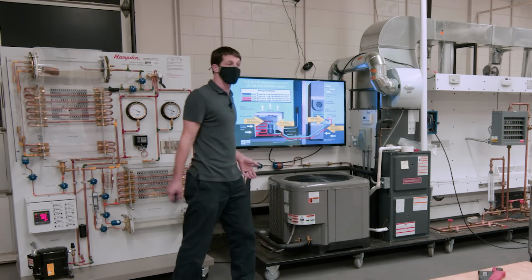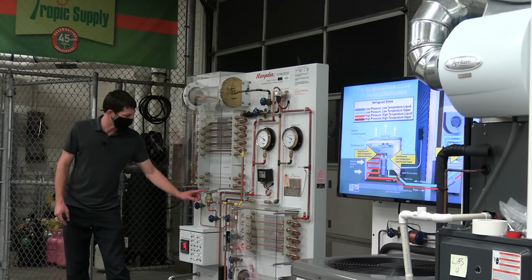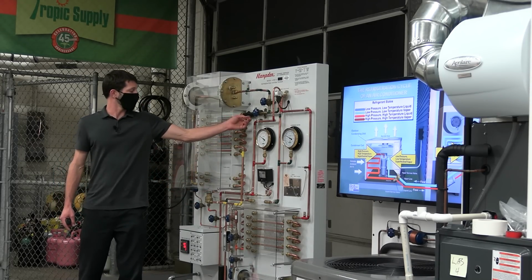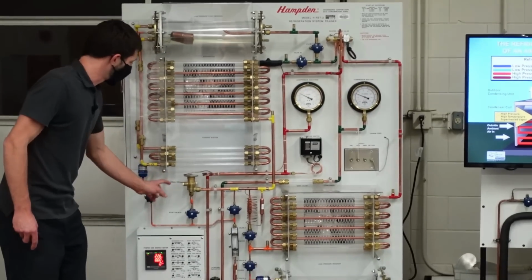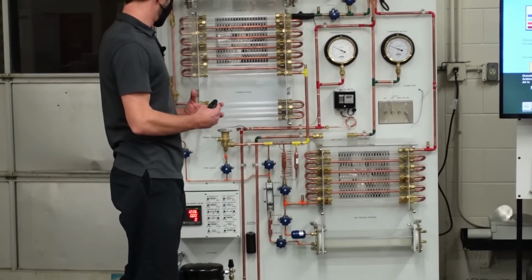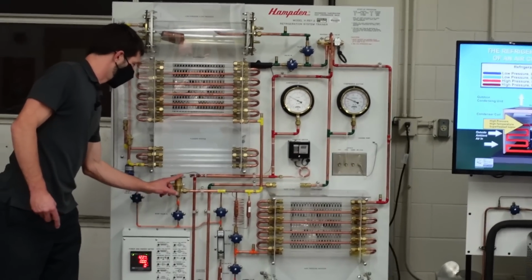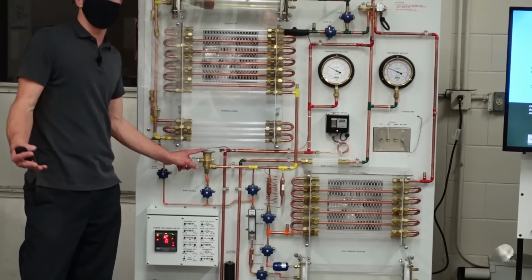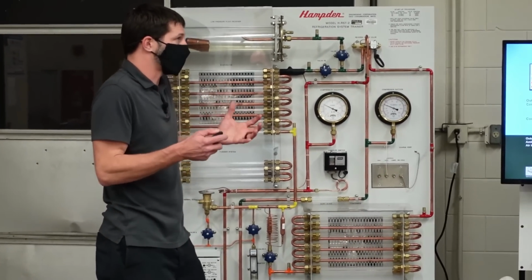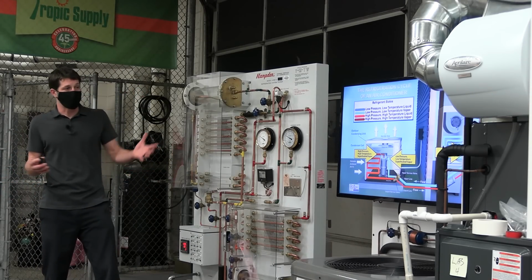Well, that's all because the head would rust, and so you would leak refrigerant out of the top, and the bulb would no longer be any good. The bulb is mounted right here, and so the bulb would not apply opening force to the thermostatic expansion valve. A lot of TXVs got a bad rap because this was just standard metal, and a lot of the newer ones are all stainless steel. So a lot of old technicians may not trust the thermostatic expansion valve, but that's the norm out there for these systems.